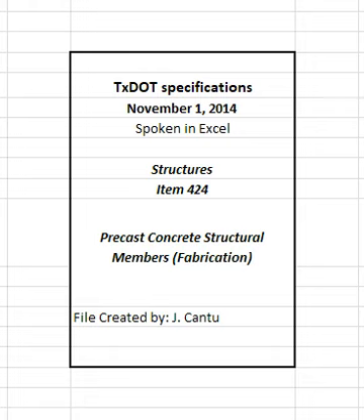Pretensioning. The application of prestressing force to the tensioning devices before casting concrete. Post-tensioning. The application of prestressing force to the tensioning devices after concrete has hardened. Tendon. Any single unit used to apply prestressing force to the member. For post-tensioned units, a tendon is a bar, group of wires, or group of strands with common end anchorage.